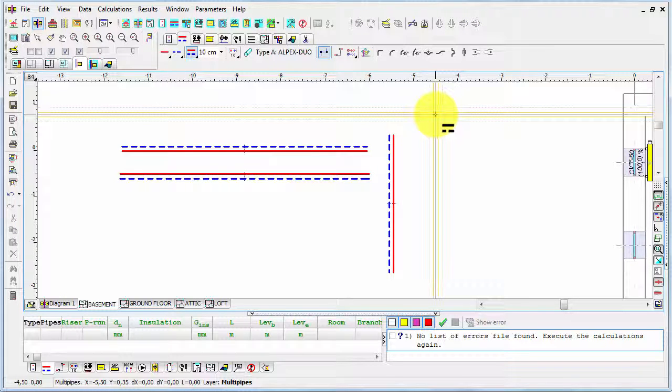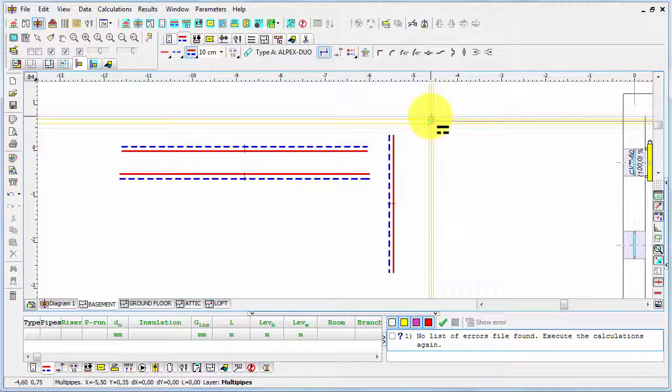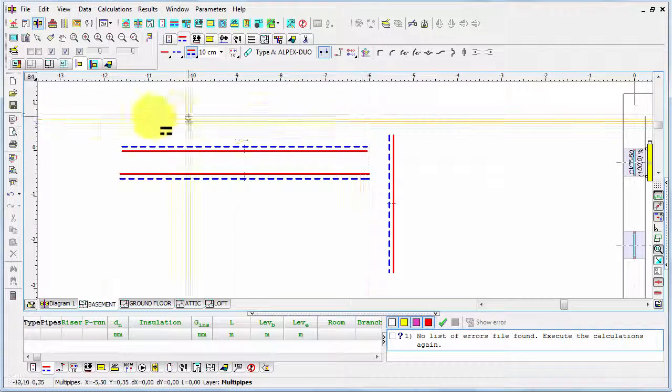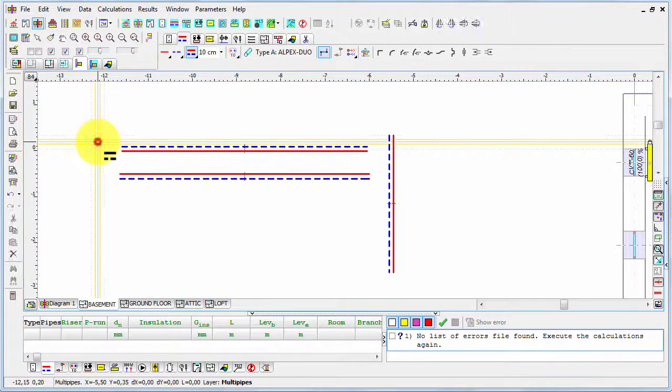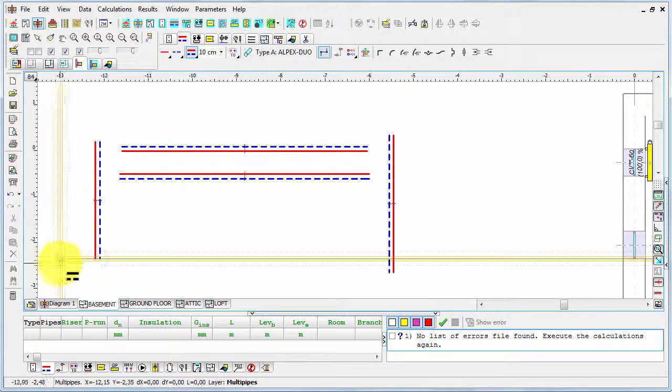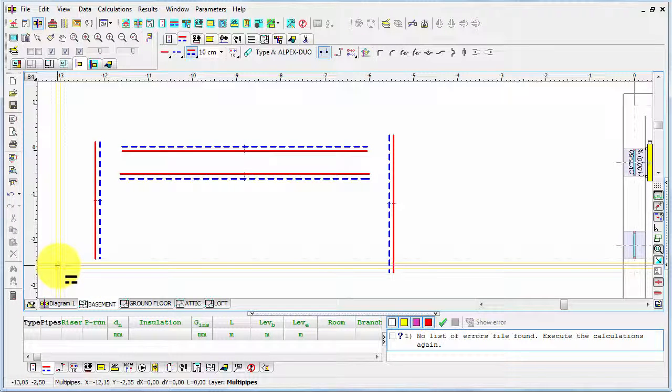Now the supply pipe is on the right because this is our right hand side. And when we draw downwards, then I hope you're not surprised that now the supply pipe is on the left from the drawing perspective, because when we are drawing downwards, that was our right hand side. And this is the basic principle, the standard one, but if you wish, you can change it.